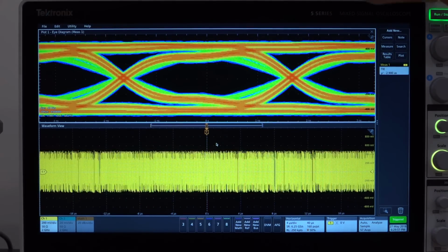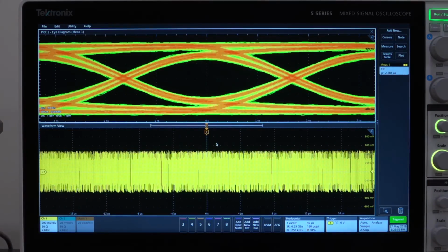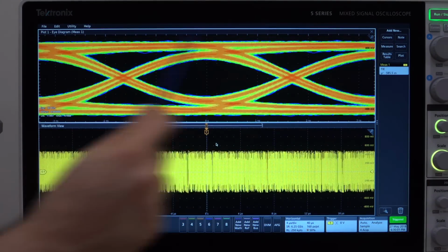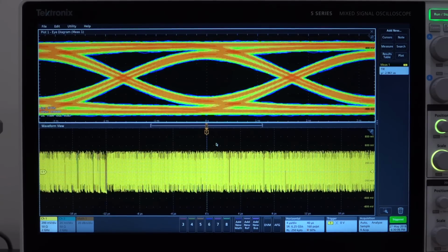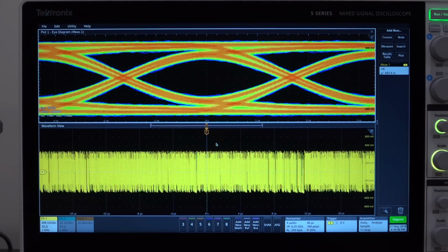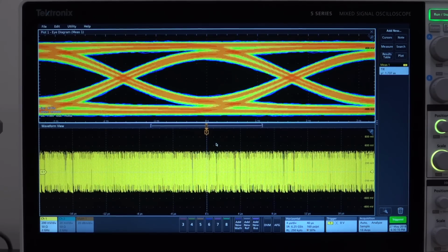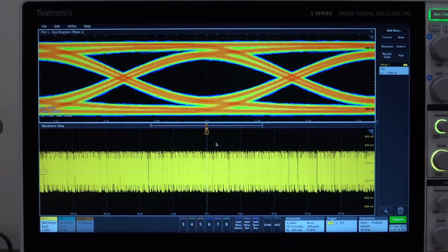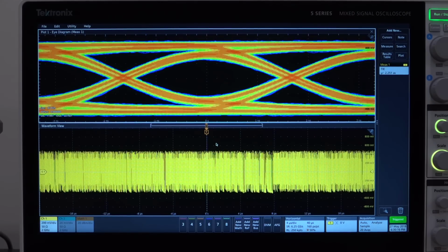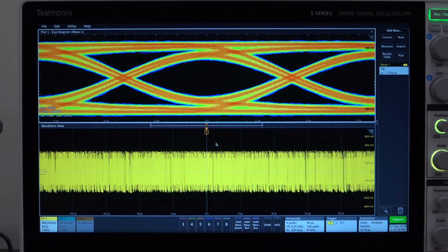and we can clear it. And you can see that this would close the eye even more, and we have a much more sinusoidal, soft transitions from the top and the bottom of the eye diagram. So this is a couple of the tests you can do directly on this type of signal. Now, there is one other thing you can do by combining the two outputs to emulate the effect of ISI, which I think is worthwhile experimenting.